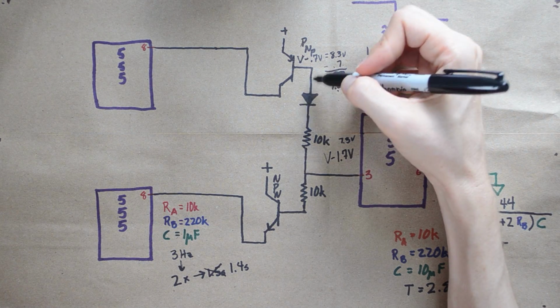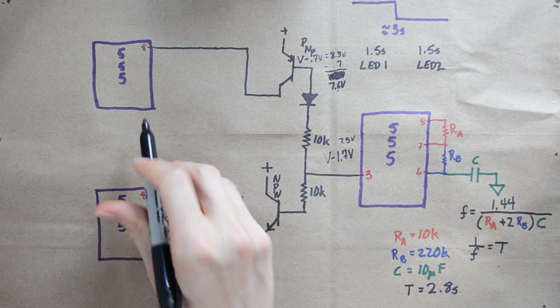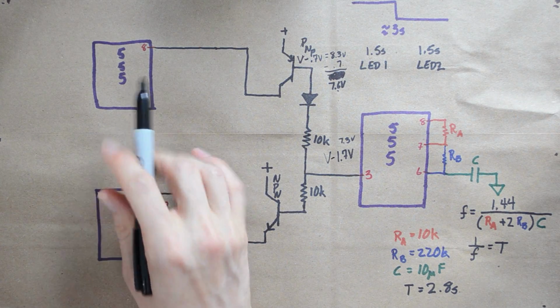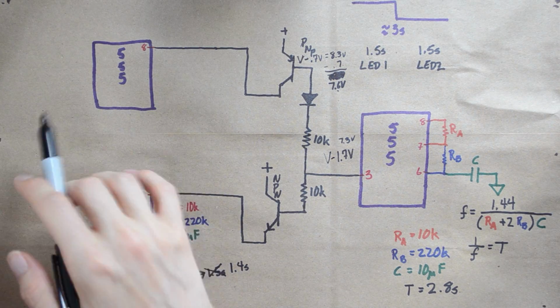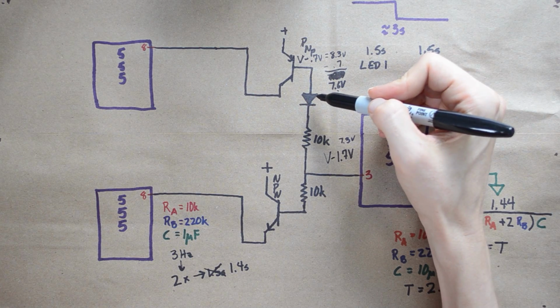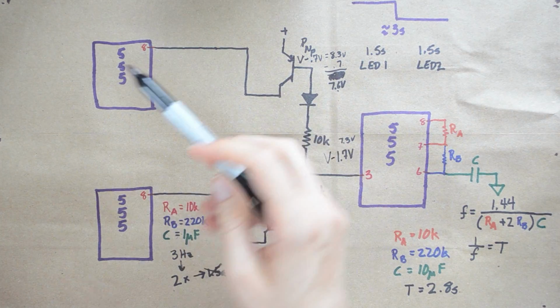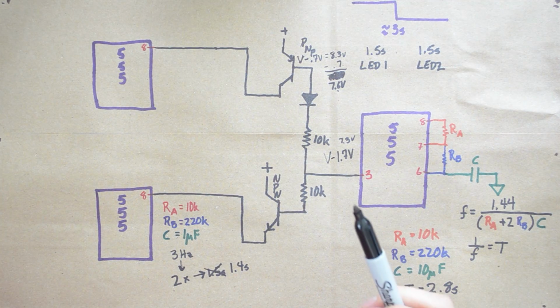There's still a little bit of current that can flow through, but this resistor kind of takes care of it, and it truly looks like this 555 timer doesn't cause the LEDs attached to it to blink. So this diode just kind of does double duty for you. It's because when this goes to 0 volts is the only time you want this 555 timer to turn on.